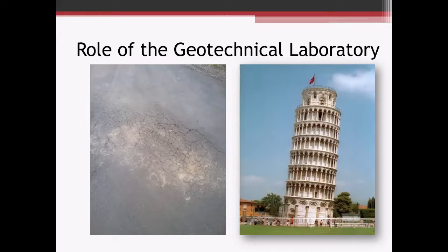This afternoon, I'll be talking about the role of the Geotechnical Laboratory. One of the challenges we face as geotechnical engineers is determining design soil parameters for a heterogeneous material such as soil, which can vary both vertically and horizontally below the surface, and sometimes in a very short distance across the project site. So we typically have to rely on experience and judgment from the information gathered during the field investigation, as well as the laboratory testing performed on representative soil samples taken across the project site.